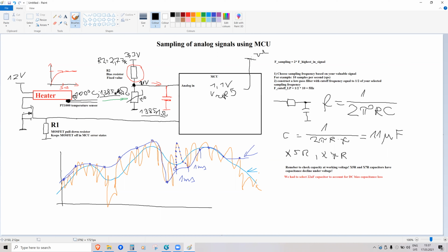So if the power supply jumps or falls or has some spikes, then the voltage reference will also be a little bit off, because usually there's some fast reacting circuitry which filters it out, but still there will be some. So at times you will have a slightly wrong value sampled. And the trick that people use to filter these things out is the following.